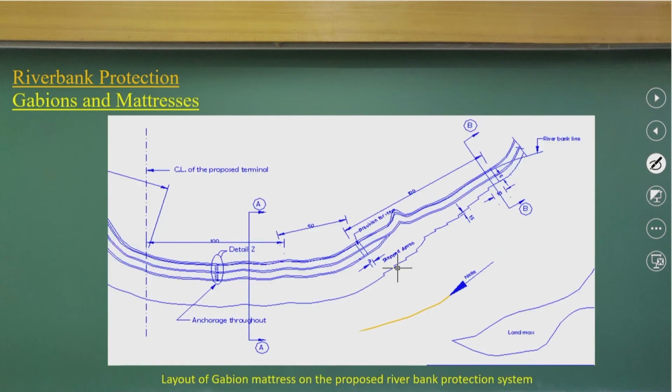And if you look at that part, we have designed for similar conditions for the Brahmaputra river. Okay, and this is a plan form. This is the jetty location. We tried to design the protection of the jetty on the Brahmaputra river. The design velocity is about 5 meters per second. The scouring depth goes beyond 30 meters. Okay. So, we tried to protect these things, that is what we designed.